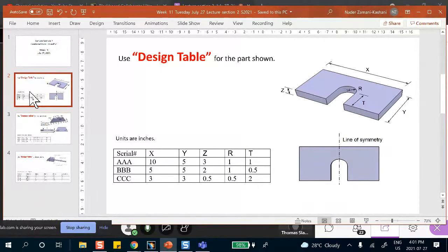However, it could be that although you can do it, it's going to be totally pointless because you know that the company that you're working with, and this guy is a client of, only makes these things in specific dimensions, etc. Okay? So there's no need for you to go and input 12.5 because you know that the company does not make 12.5 inches of a thickness of something. They make 12, they make 13, etc. So this is where the concept of design table comes.